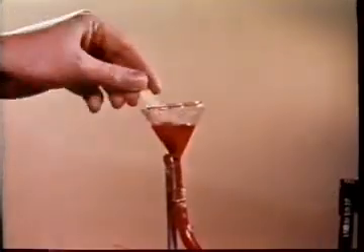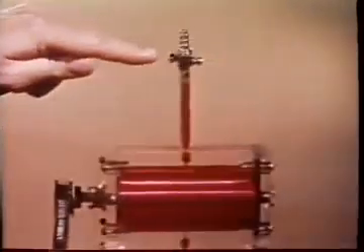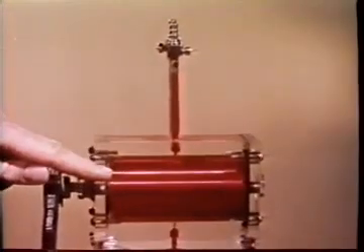In this case, the journal has been filled with syrup. By sealing the journal from the atmosphere, such a strong negative pressure is built up in the diverging section that cavitation bubbles appear. The bubbles get longer as the speed increases.